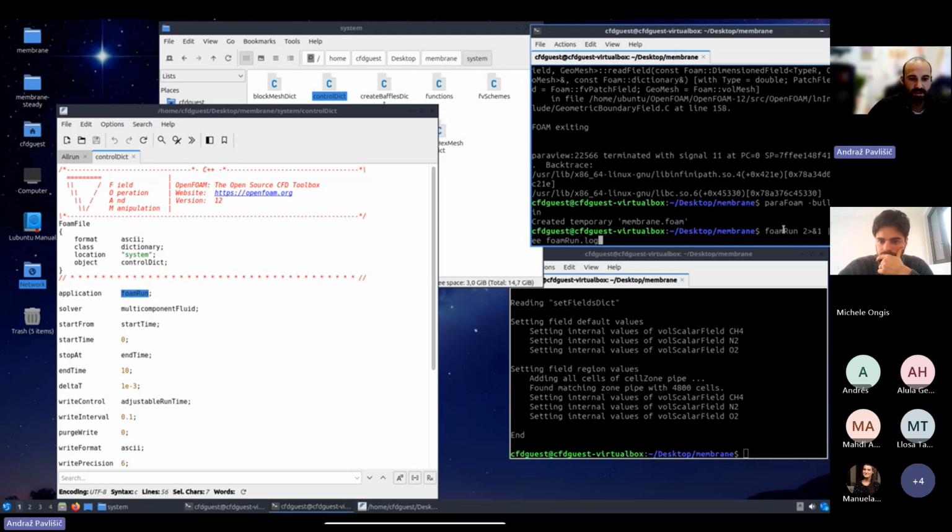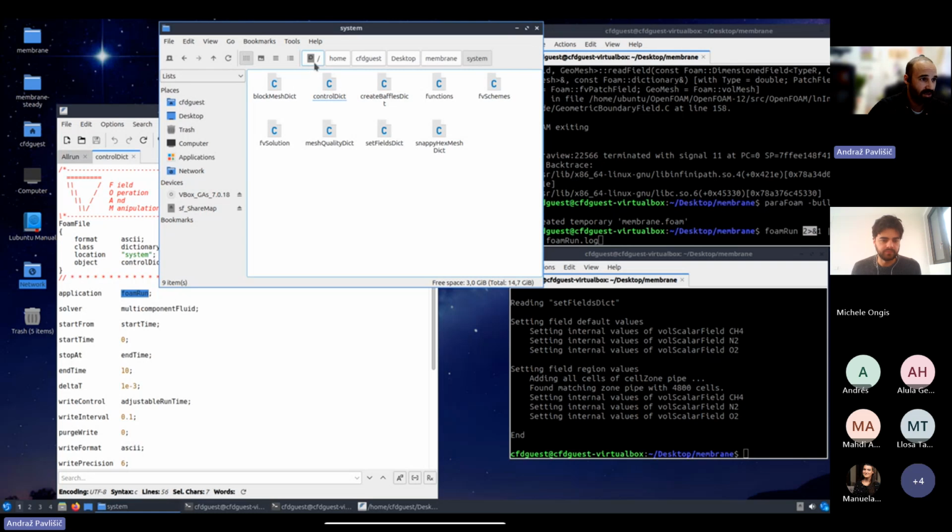And you can see here, I'm trying to call from the terminal this command foamRun, but those other things that are written here say something like this: everything that is calculated, please pass it also to the terminal itself so that I see which calculations are running in the background, but at the same time also write a file called foamRun.log, so that everything I can see from the terminal is also written in our working directory, which is here.